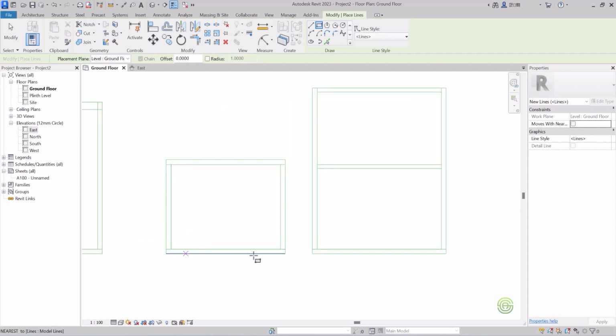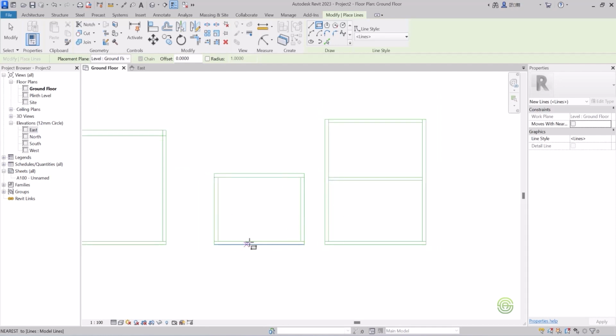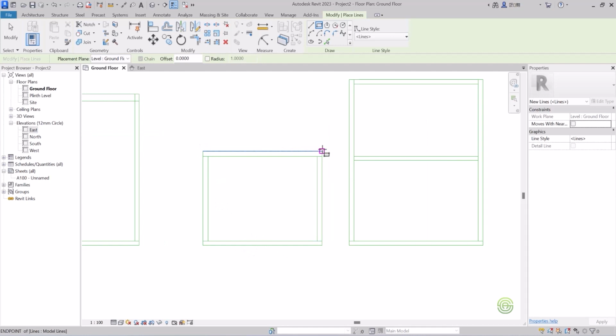This is one method, and this is the other. Here you are creating a floor slab and then walls and again a floor slab. Here in elevation, you will see this floor slab band running across the whole floor. So this is also a correct method. In these two, you can choose any one. So now we'll see this method, like floor, walls, and then complete floor. We'll just use this method for now. If you want, we can proceed with the other method also, but in this class we will select this method.